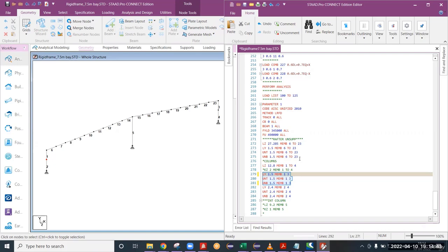Yep. If you take rafters, there will be purlins running over the rafter, so there will be continuous support where the purlin is located at the top of the rafter. So leave LY and UNB aside first. UNT means unsupported length of top flange. It is 1.5 because the purlins will run at every 1.5 meter spacing. That is why we have considered 1.5 for UNT.